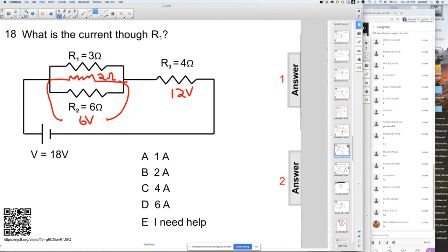Okay, now you could have just found by using this 2 ohm resistor, V equals I R, which was, what was I? 3 times 2 is 6, right? I was 3, if you remember, times 2 is 6. Or we could have said these two got to add up to 18, so this has got to be 6 volts.